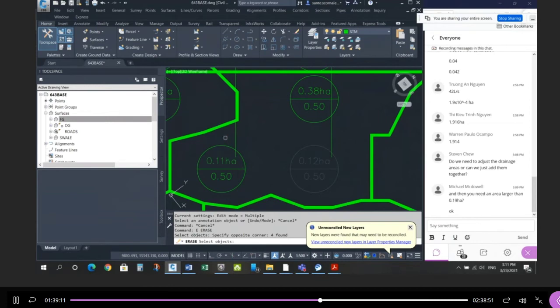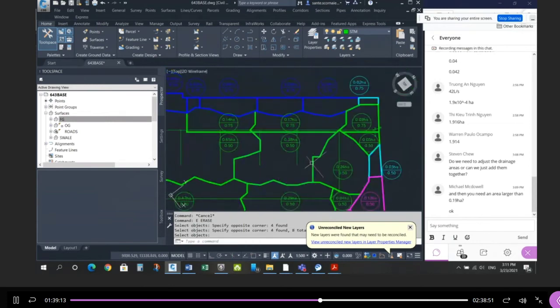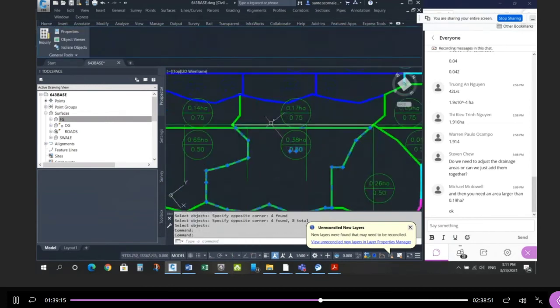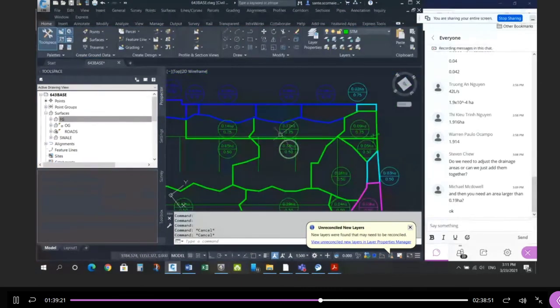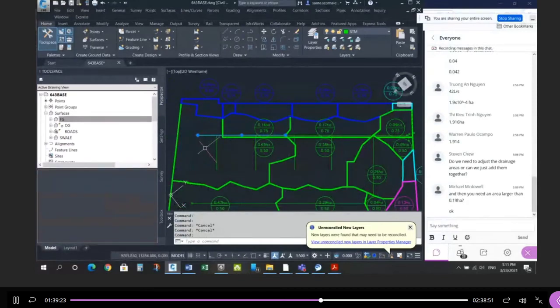And I would get rid of this, and I get rid of this. And now I have the area that's got this runoff coefficient to calculate and design this pipe, and so on. So now, if you have 8 pipes, there should only be 8 areas, except for the ones that have more than one runoff coefficient. Okay? And only these interior pipes need to do that, right? These areas out here, we're not going to combine them to what's happening here. We're not going to redraw them and combine them. We're just going to add the numbers on the spreadsheet. I'll show you that when we do that a little bit later.